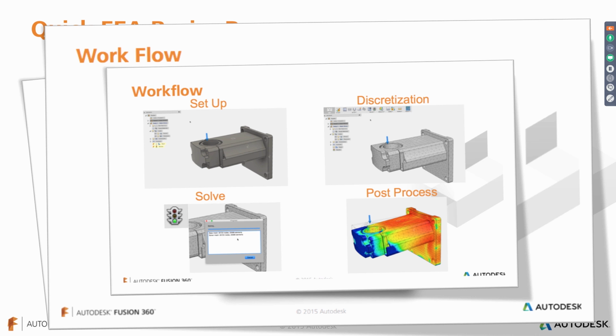So the basics behind the workflow is to set up your problem, to define boundary conditions, to define loads if you're doing a static stress analysis, to define thermal considerations if you're doing a thermal study. Once it's set up, you get into discretizing. That's where you break up these complex models that you're all working on into small elementary pieces, tetrahedrons in our case, and that's when we can go ahead and run the mathematics, solve it.